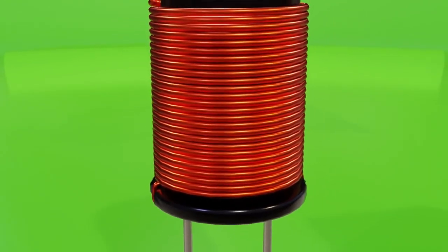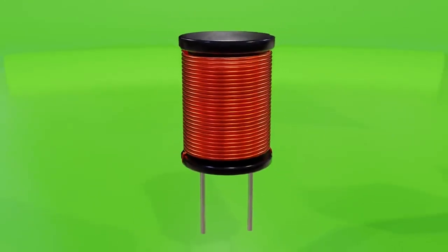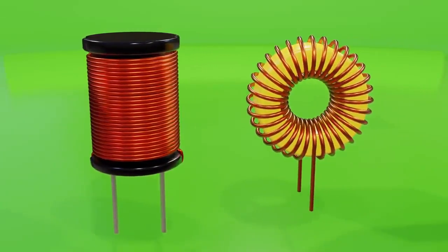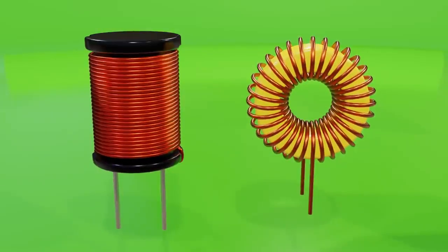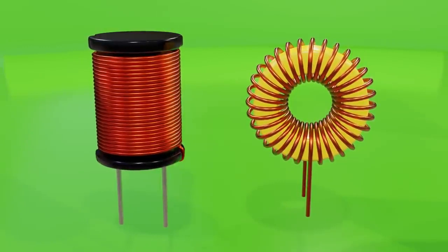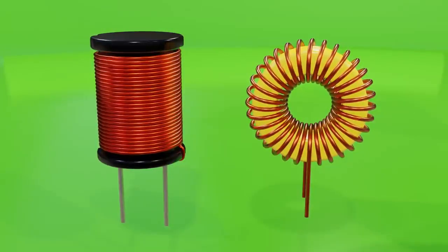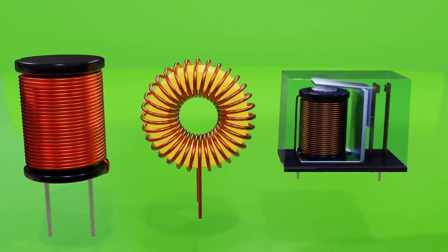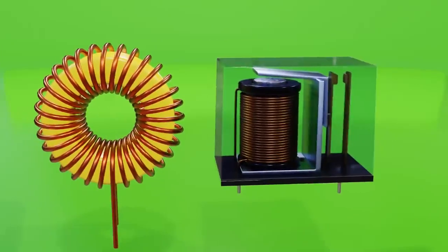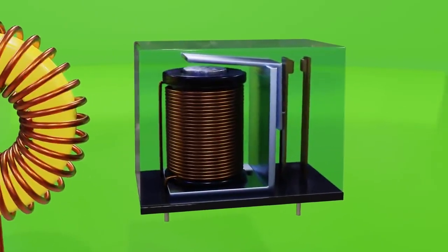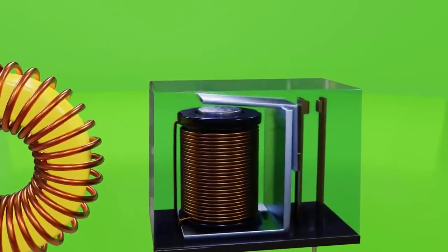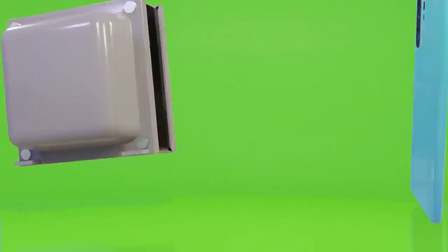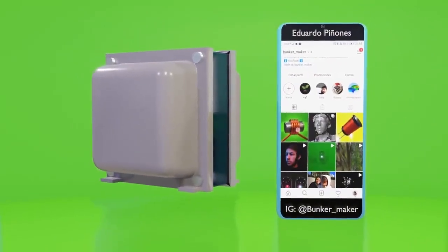Because of all these characteristics, inductors, or coils, are an extremely versatile element. If we concentrate on their ability to generate a resistance to current changes, they can be used in signal filters in a similar way to capacitors, or to stabilize the current delivered by a power supply. On the other hand, if we focus on their ability to generate a magnetic field, inductors can be used to move other elements by acting as an electromagnet, which is exactly what happens in a relay. Besides this, the electromagnetic field generated can also be used to induce currents in other inductors, as in the case of transformers or cell phones with wireless charging.